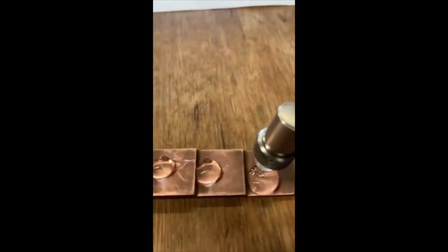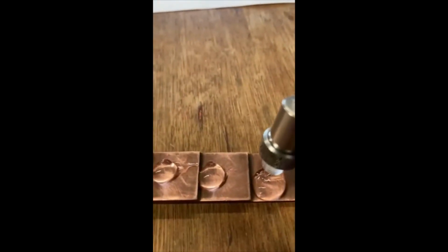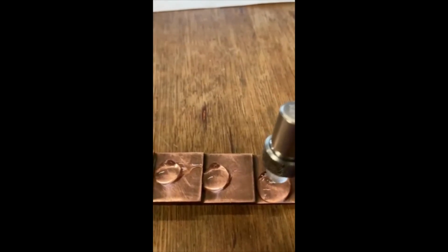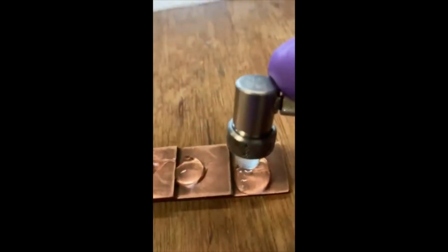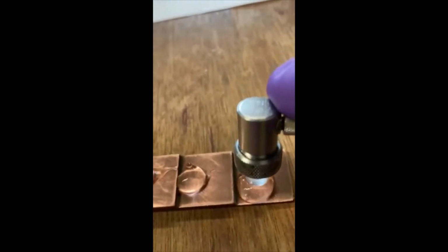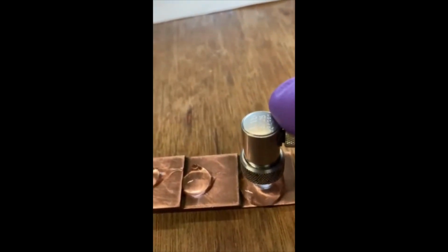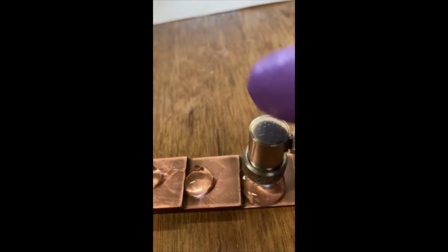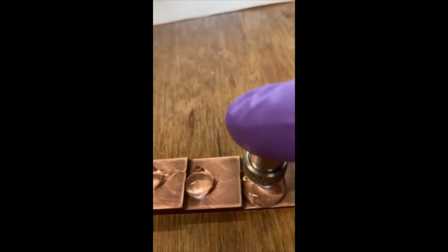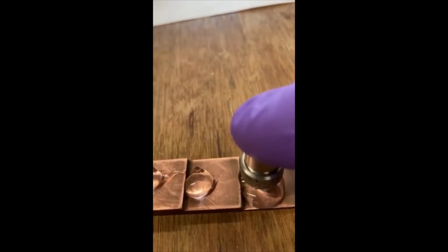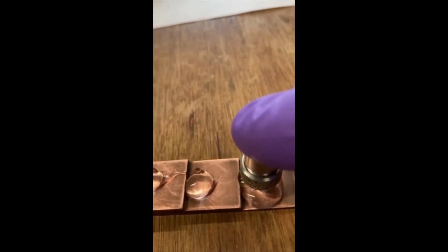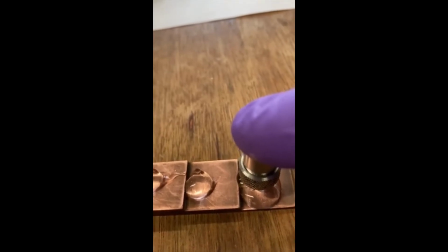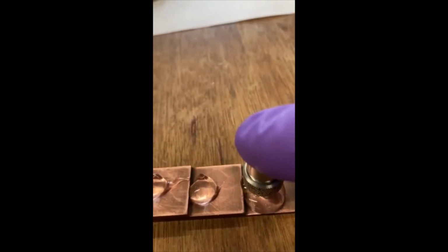Here, the back side of the copper has poor connection to the table, and an air gap exists. Therefore, the pulse, when it passes through the sample, will reflect from the back surface, heading back towards the transducer, where it is, in this case, measured by that same transducer. The surface of the sample pushes against the transducer when the wave returns, and the transducer measures that pushing on the surface and converts it into a signal that can be read on the oscilloscope.